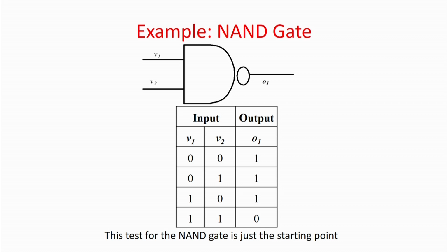So why is it possible? Because we are able to make very complicated systems like NOC and SOC on a single electronic circuit chip. How is it possible? Because we are continuously shrinking the technology from 5 microns to 0.45 or even lower micron technology. Lower micron means that in the fabrication technology, whatever lines and wires you are drawing, the distance between them is shrinking. Once you start shrinking the distances, the problem is that a lot of failures